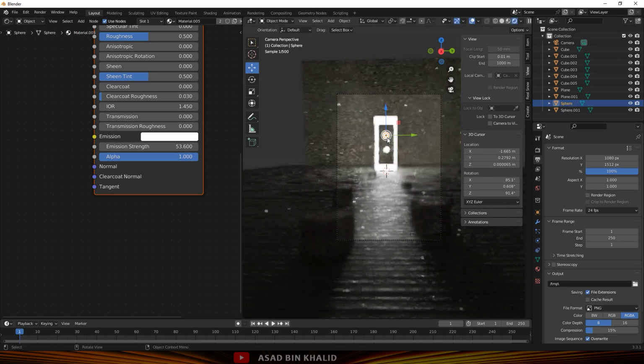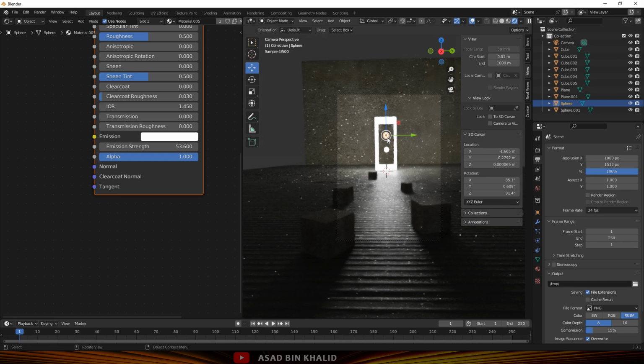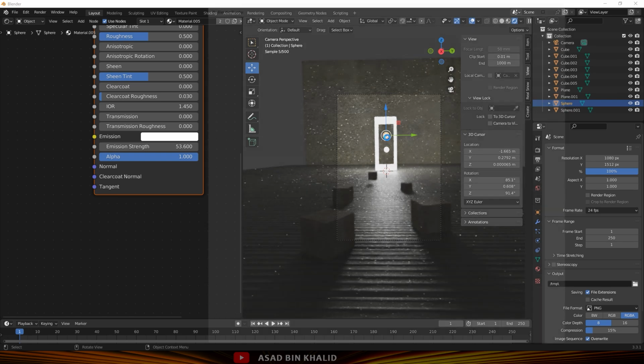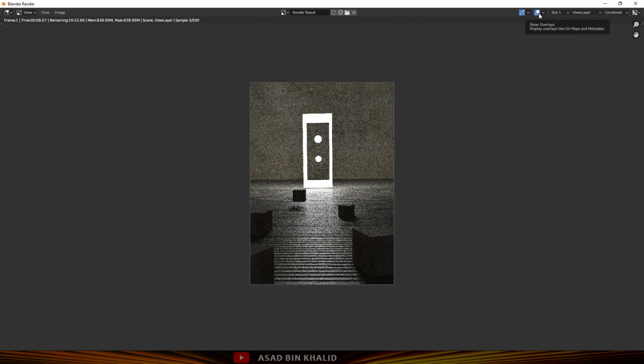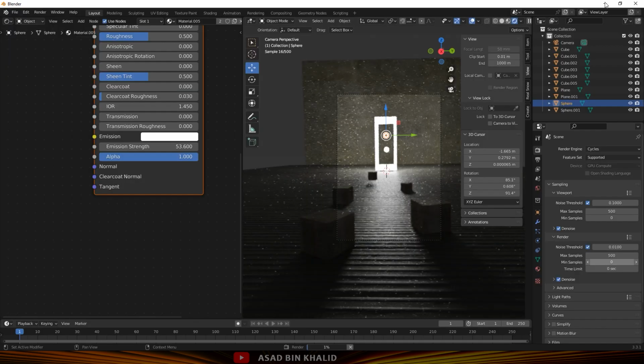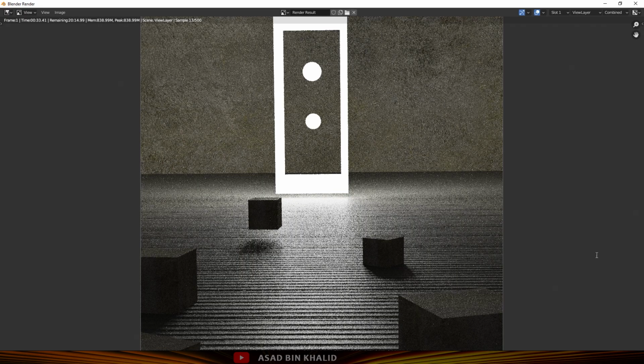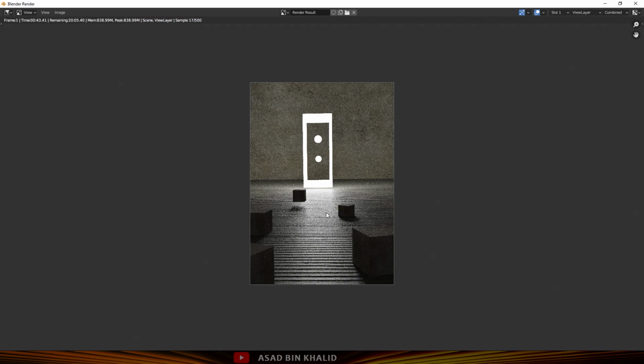And guys, of course, you can do some after work as well, just render it and then go back to Photoshop, add a white background and everything like that. Make sure when your test render is complete, go back to settings and turn the samples up to like 40, 50, let's say. That way it makes a perfect, high quality render, like 4K. So this is a simple but very effective tutorial, guys. Maybe you can add texture, and I just wanted to show how things work. So hopefully this makes some sense for you.